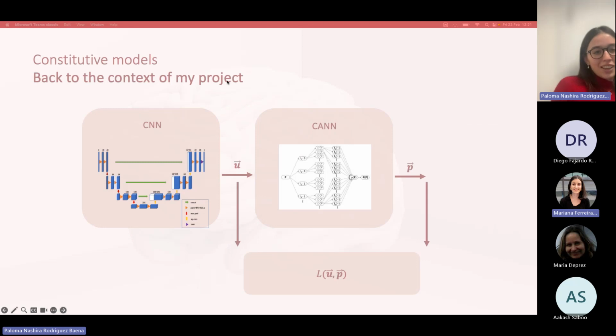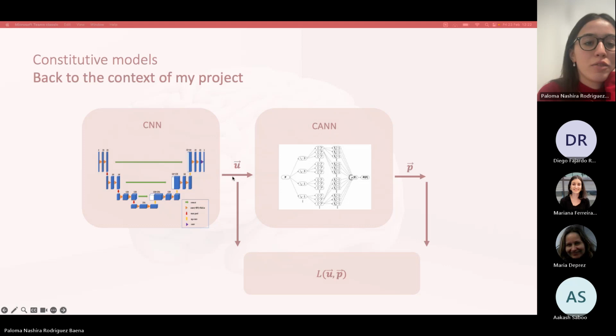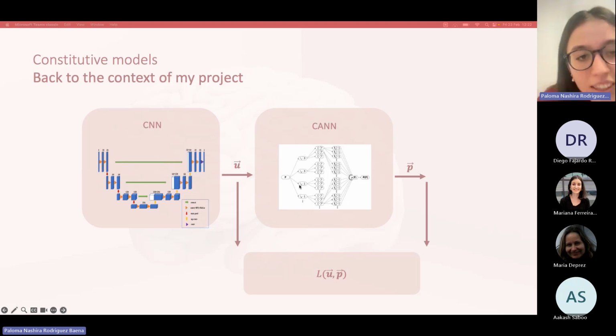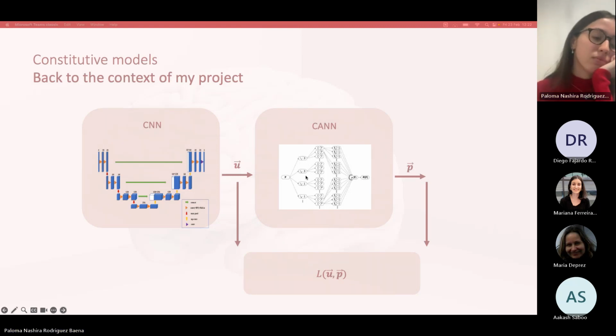You mean? Yeah. So we have the neural network, which outputs a deformation field. You can decompose the deformation field into the invariants, deviatoric, the stress-free configuration, and that would be the input in the beginning. But we only need I1. And so basically, instead of outputting the parameters of the deformation plus the 6 independent values of the stress tensor, you only have to output the deformation, from which you estimate this using the physical law.